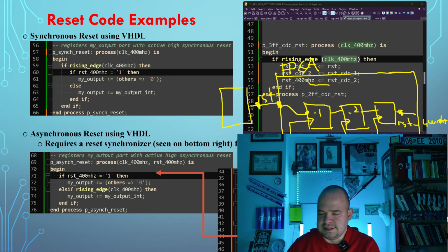So in this example, again considering that PVT is good and 2 flip-flops are enough for this reset synchronizer, there is of course a probability of having this first output metastable, because that reset_400MHz_pre is changing its state from 0 to 1 when it is going to the rising edge of the clock.